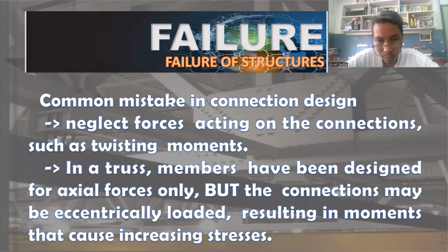For example, in a truss, members have been designed for axial forces only, but the connection may be eccentric, so we need to consider and use the proper set of formulas. Without which, it would result in increased stress, and ultimately, if we are not careful, failure of the structure.